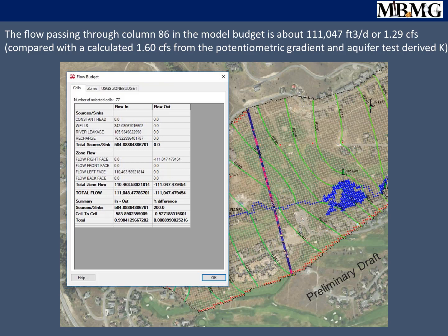But I worked out that it's flowing about 1.5 CFS through the model, whether you calculate it by hand or look at the model result. And that's all I wanted to say about this: the numbers are about right. They differ slightly, but 1.5 CFS through that entire section, moving through the aquifer, and that's 120 feet a day.